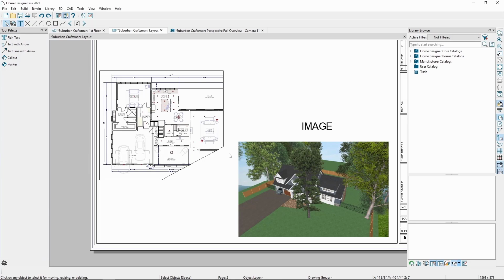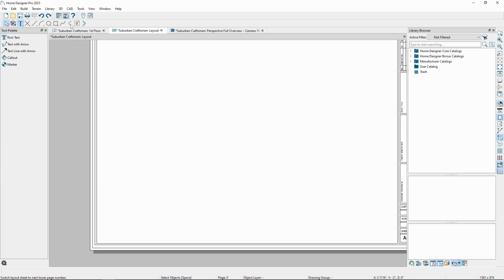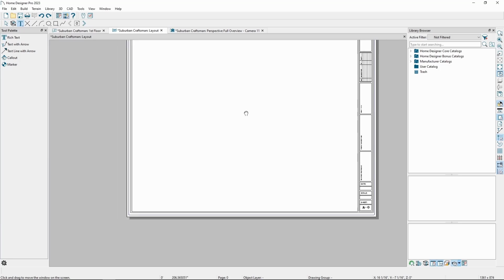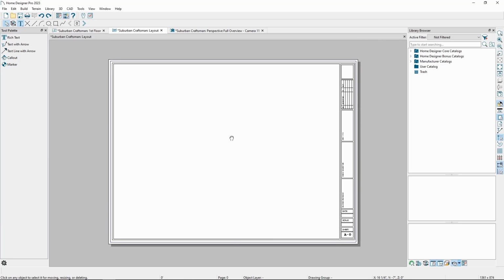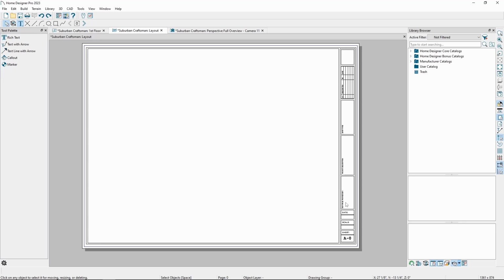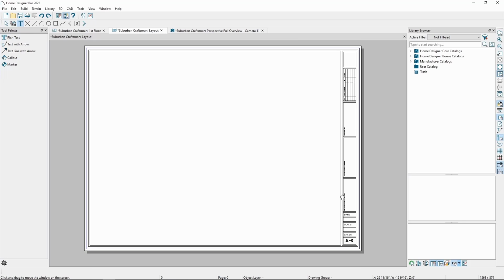We call page 0 of the layout the template page. This page acts as a template for all 5 subsequent pages, meaning anything visible on page 0 appears and cannot be selected on the following pages. So, we'll want to add anything to page 0 that we want to see for every following page. For example, we can add a drawings provided by name on page 0, since that might be something we'll want to see on every page.